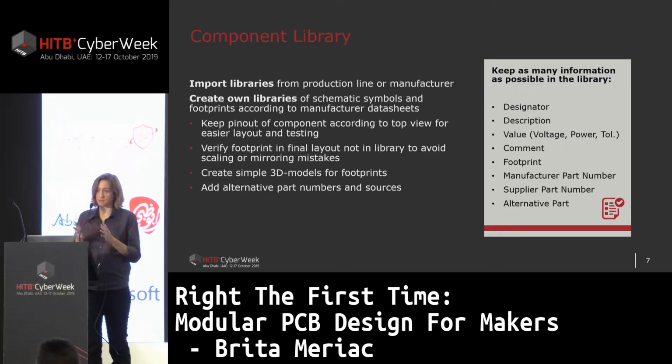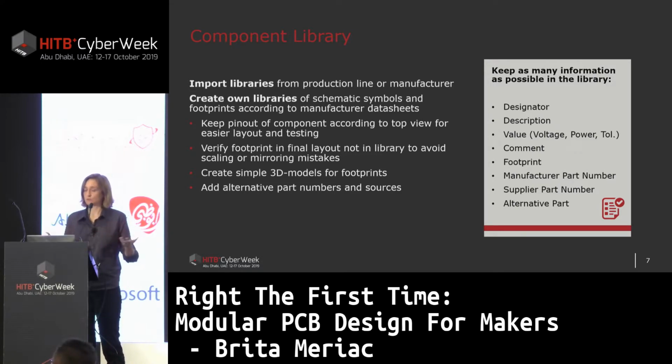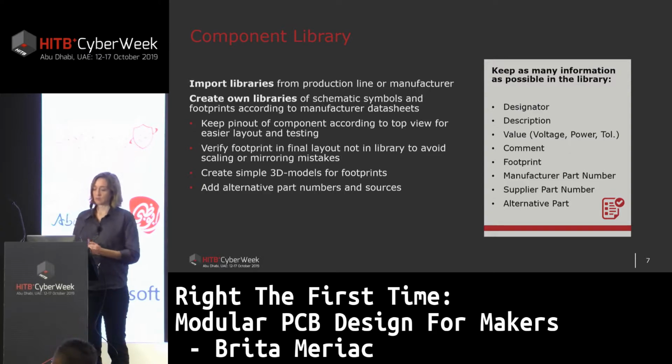There might be some mirroring mistake or some scaling mistake. And a simple thing is to add a 3D model, it doesn't take much time. It can be just a box with the correct height, but it will help you later to design a case or to show your PCB in a picture.